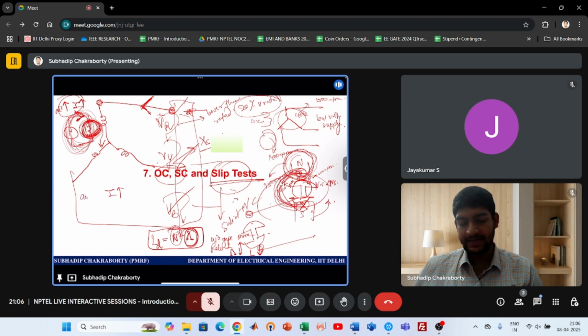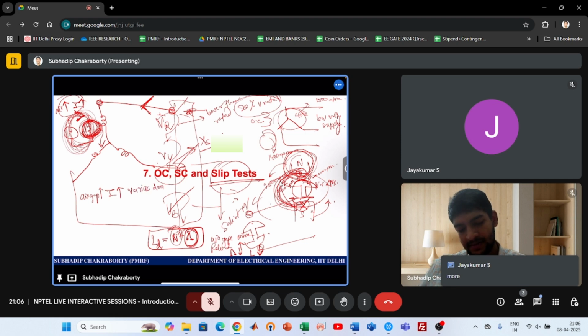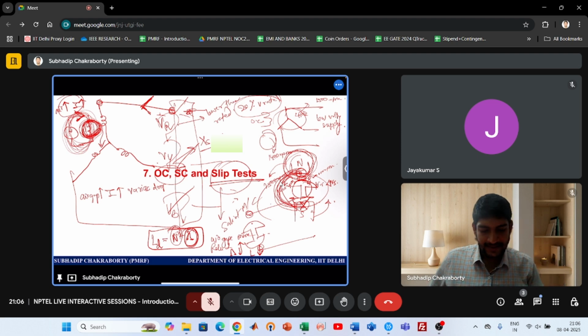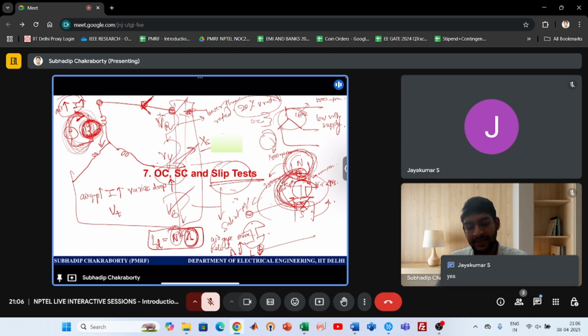More air gap, more variac drop. That is the drop, a small drop happening at the variac, this supply transformer. The variac drop is more, right? Because current is more, I into small impedance. So this terminal voltage reduces. So these positions will come many times.